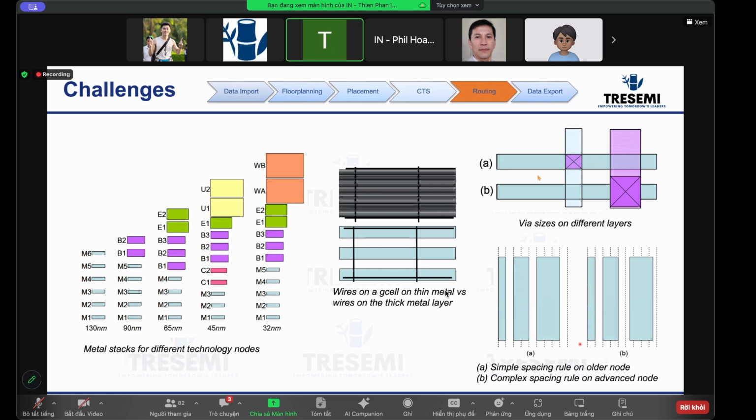All the RC, all the timing tables, all the extraction, all of those numbers are no longer valid. So for thickness you can't. Just think of that as a quick check. If you change something and your model is no longer valid, then that means you just can't do that. There's no way in the design database you can change the thickness because it came from the model.